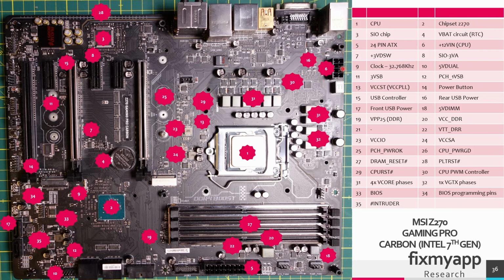This is the CPU power connector. On one row it is connected to ground and the other one will get the 12 volts from the power supply. This power connector will deliver the necessary power to the CPU. These connectors typically come in the form of 4 pins or 8 pins. The power supply for the CPU is separate from the 24-pin ATX power connector because this power connector is designed to handle high current and power demands that the CPU needs.